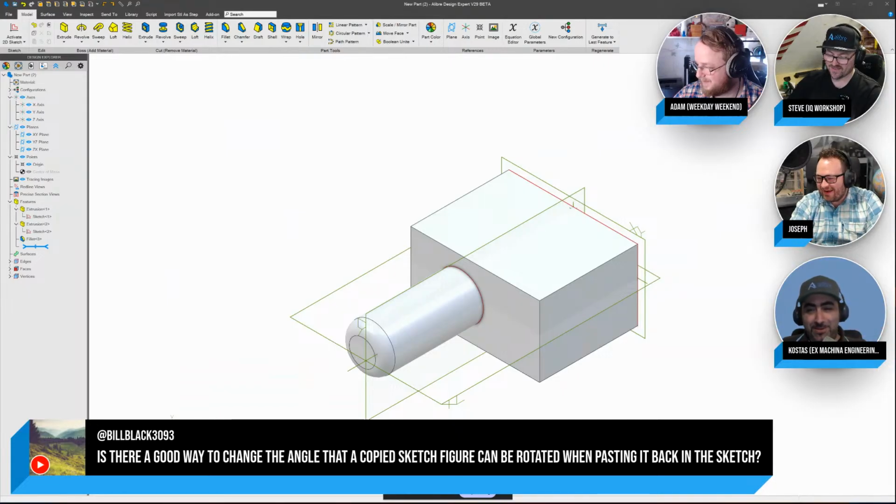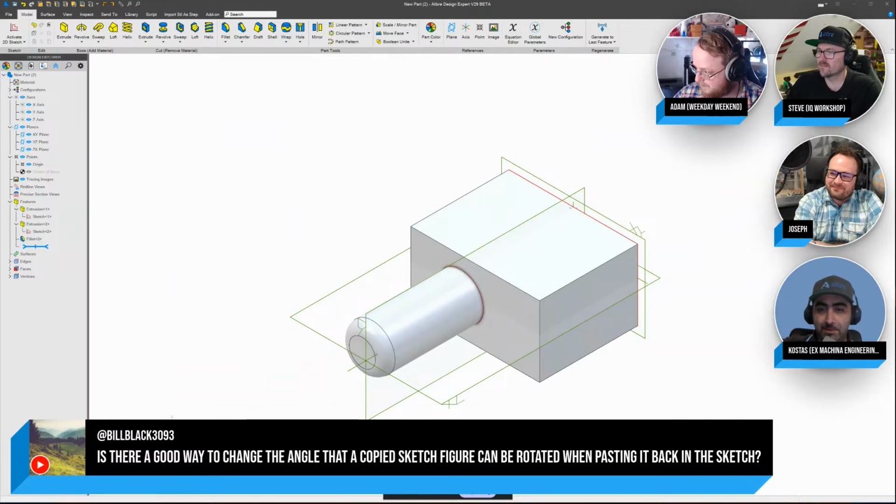What you need to know there, Bill, is that when you're using the paste stamper, when you copy with a base point, then you can use a paste stamper. And when you stamp what you copied, you also stamp the constraints and dimensions.